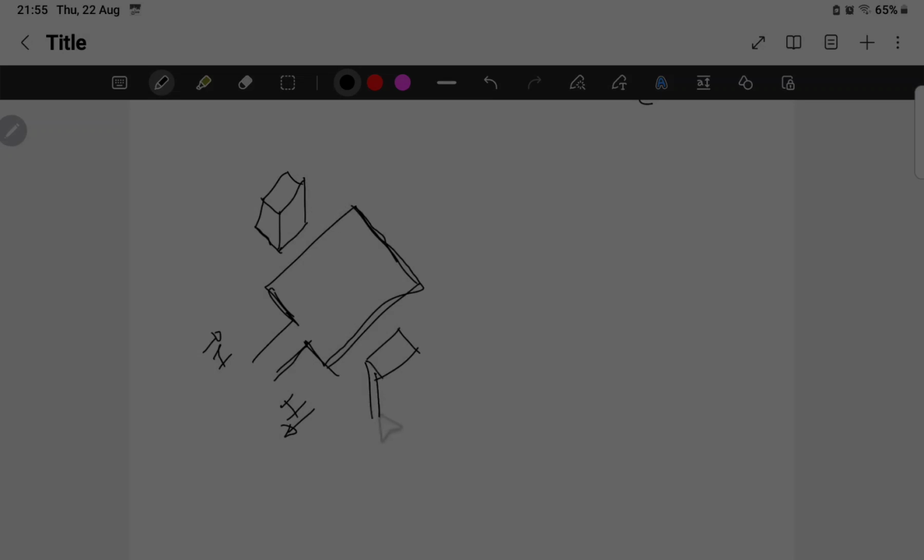Let me draw it like so. Our permanent magnets inside our electric motor, and over here we have our commutator, and I'll explain that right now. If you use the left hand rule, north to south, these lines you can ignore because they are producing zero force.